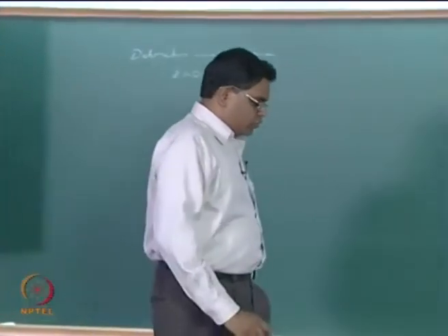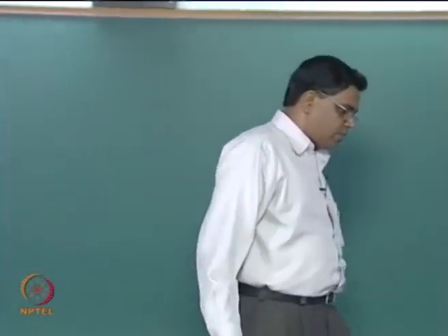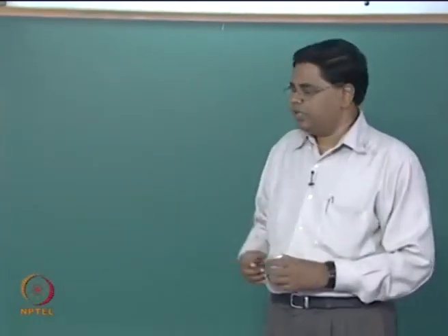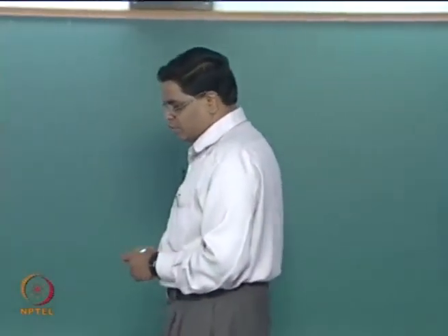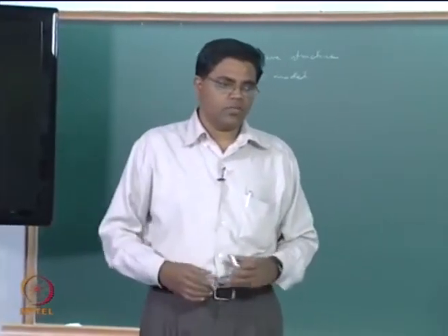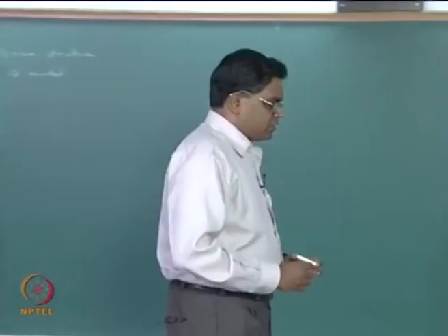So what we have done so far as far as detonation is concerned is to come up with a way by which we can get the detonation wave velocity, for which we realize that we don't necessarily have to get into the wave structure, unlike what we did for the deflagrations.